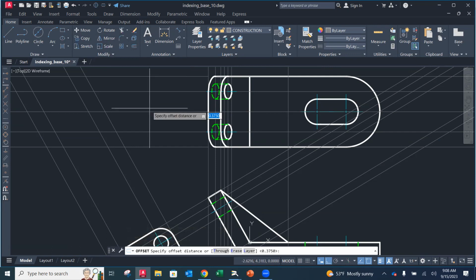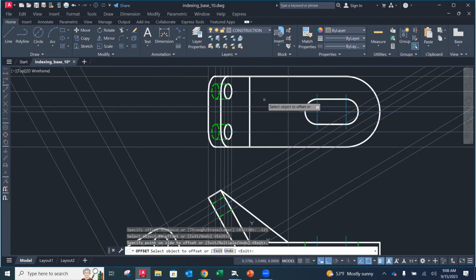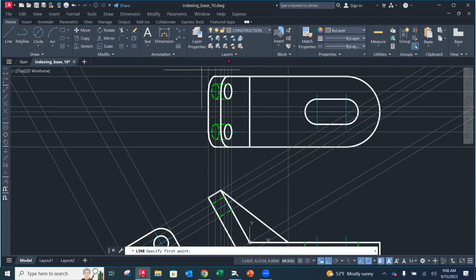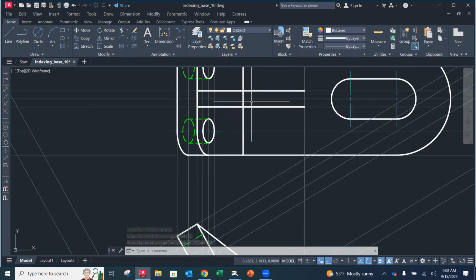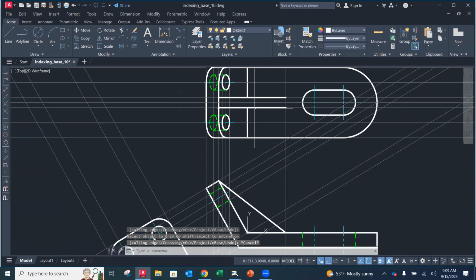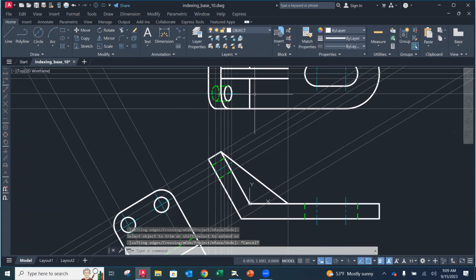Offset command. The width of that is 0.25, so 0.125 in either direction. Okay. And then my gusset is going to be, I got to do my object line layer and then my lines. It's going to go from here to here, escape. And then from here to here, escape. Now this in between, I need to trim away because that's like part of the material. So trim, I just keyed it in, I spelled it out. You can do it that way, or you can grab the icon on top. Not a hidden line in the back, okay, of this one.